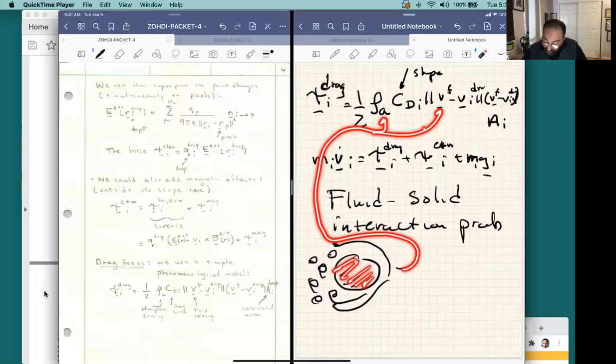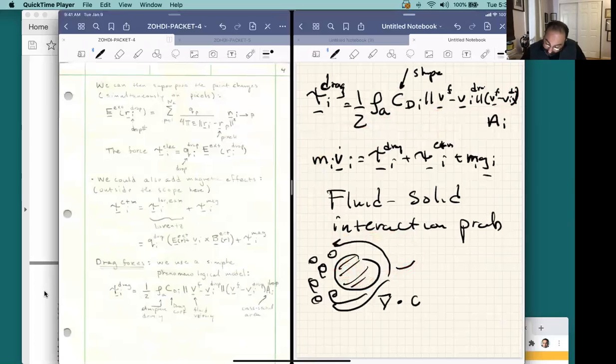Now, unfortunately, the differential equations for the fluid are also not easy. The differential equations for the fluid look something like this. They're the divergence of the stress in the fluid plus the body forces that are acting in the fluid. So there could be, for example, gravity, buoyancy, things of that sort. Those are the forces that are acting there. And then you have the density of the fluid itself again, and this is multiplied by the time derivative of the velocity of the fluid.